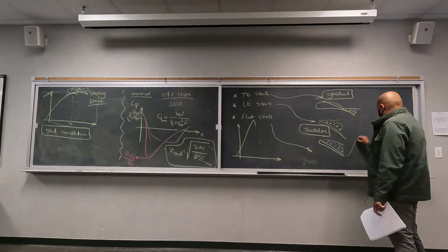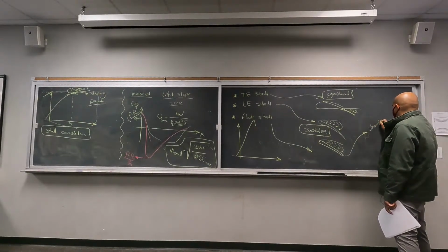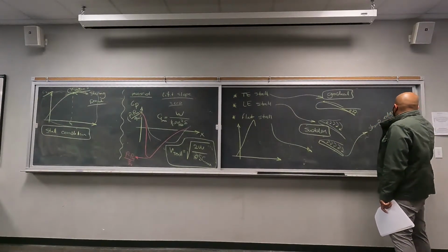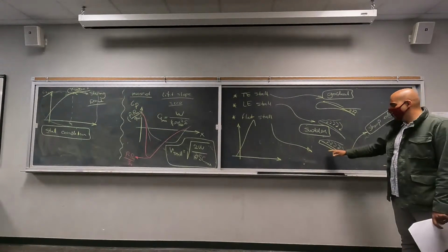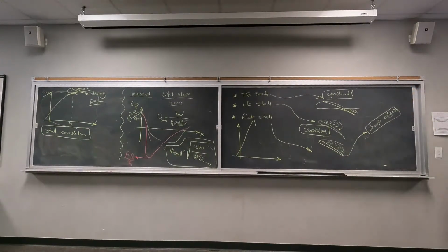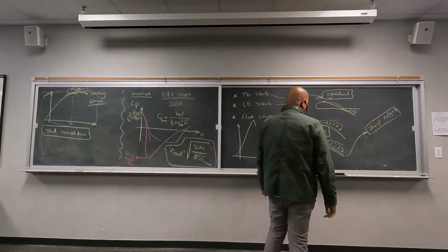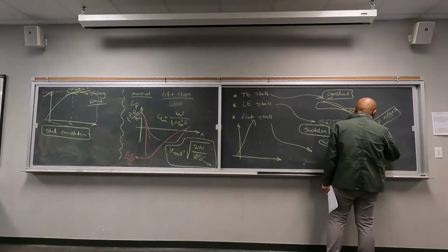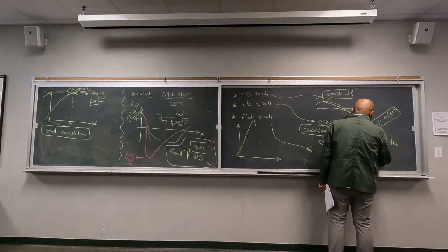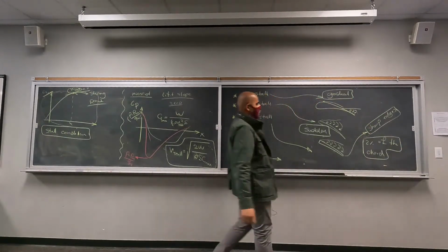The reason they stall earlier is because of very sharp edges. Your flow sees a flat plate with sharp corners, right? It doesn't mean that this flat plate has to be a sharp flat plate, but it's so thin that your flow sees a flat plate with very sharp corners. And we actually have a definition: your thickness has to be 2% of the chord for your airfoil to be considered a flat plate.